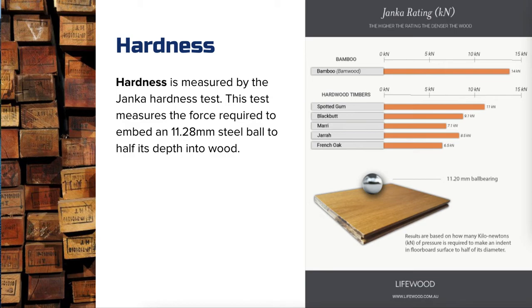Whereas I compare that to an experience I had a few years ago where I had a student trying to put a screw into some jarrah for a hinge on a door. They'd pre-drilled the hole, probably 0.2 of a millimeter too small in diameter, because they were using the drill bits available, not necessarily the absolutely correct one. When they were trying to put their screw in, twisting it by hand using a screwdriver, the head of the screw actually snapped off in the pre-drilled hole, because the hardness of jarrah is so high that it wasn't able to split or compress to fit the extra space needed by this screw. So hardness is actually something you want to consider.